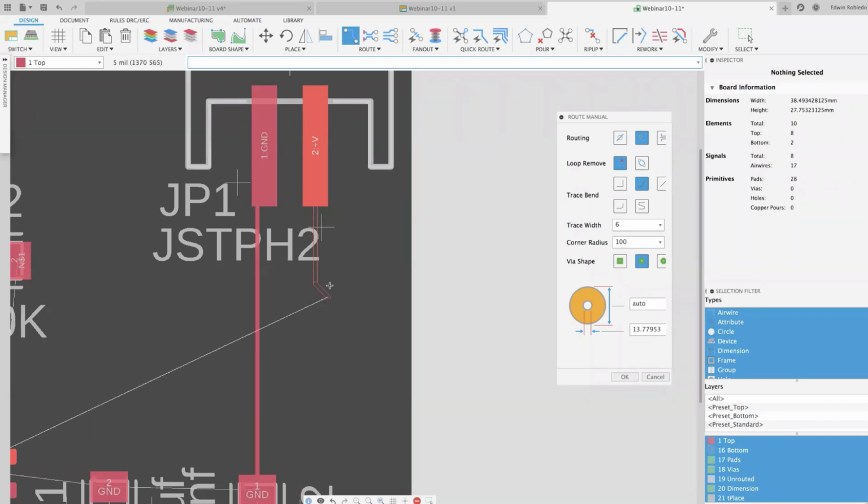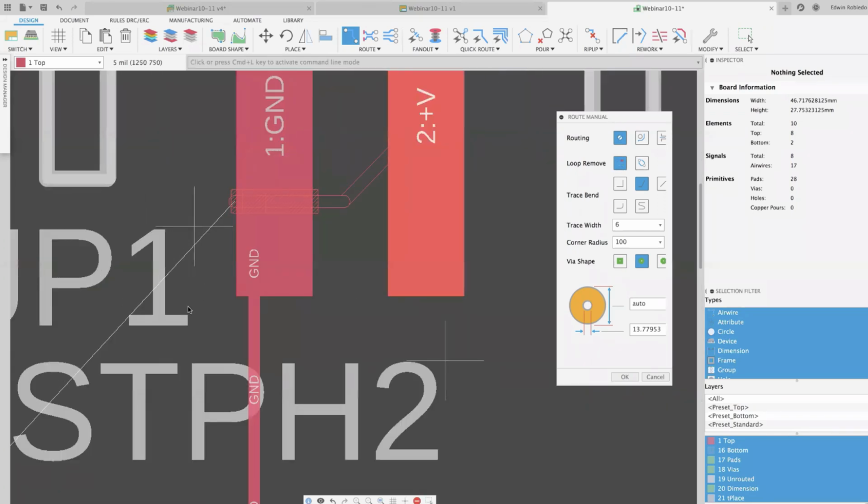It's just totally avoiding it, as you can see. Now, if I want to have full control, and there are times that you do want to have full control, I could go here and select ignore obstacle routing, and as you can see now, I'm able to go in any direction I want. Now you'll notice that I have DRC live, therefore I get the hatch markings letting me know that I am going on some violation as well.